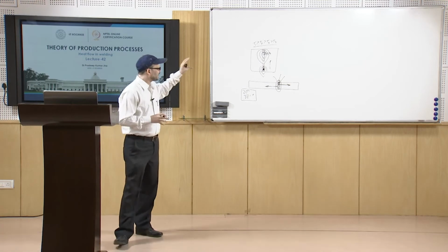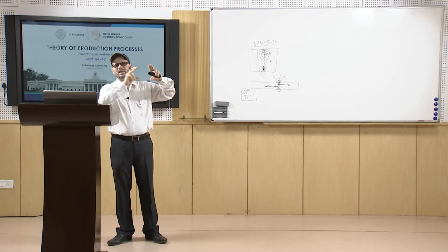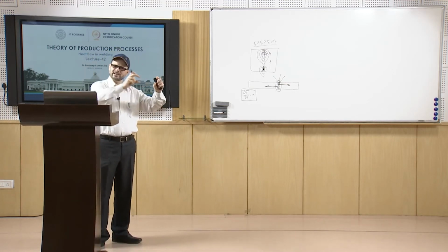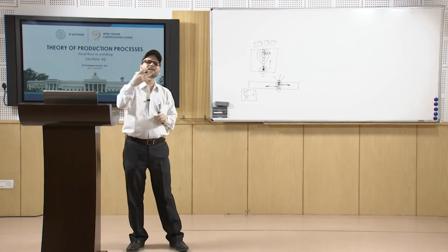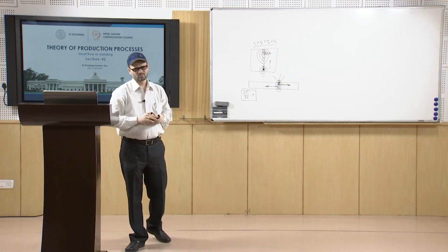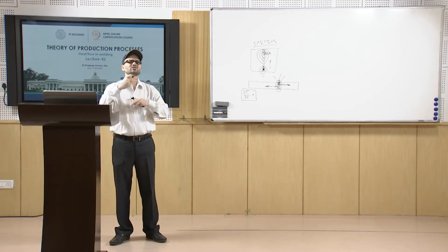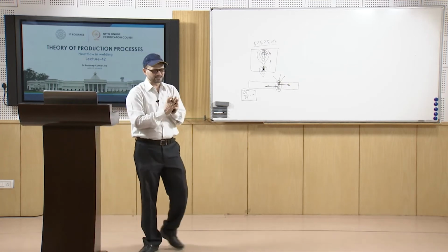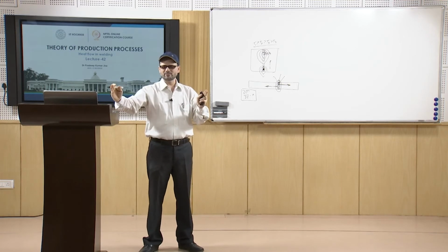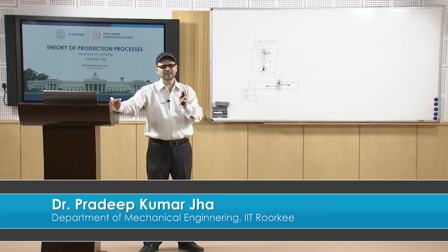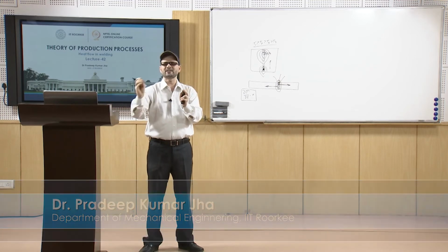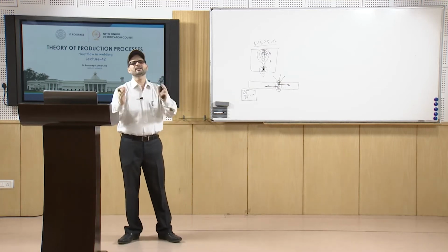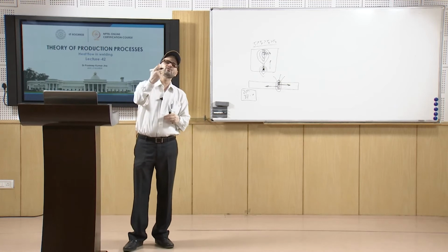So, if you take that example where you have a moving source, in that case, in the x direction, if suppose it is moving in the x direction, the x coordinate has to be replaced with certain other parameter. So, you will have a welding velocity. Based on that, you will define another parameter. Basically, what you see is that if at any point this is the x, and it is moving with speed v, then after time t, the distance will be x minus v times t. So, x distance will decrease by that. So, that way another parameter will be defined.